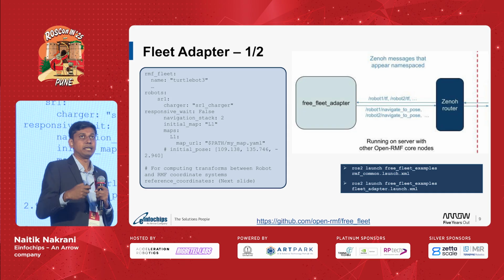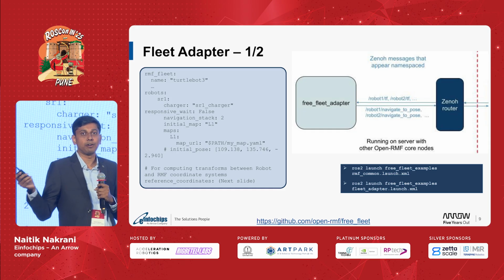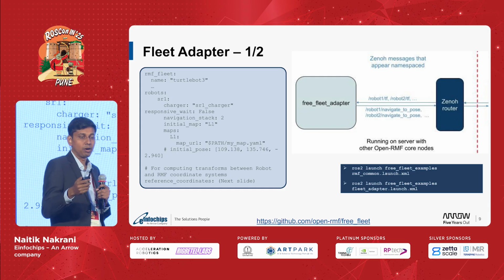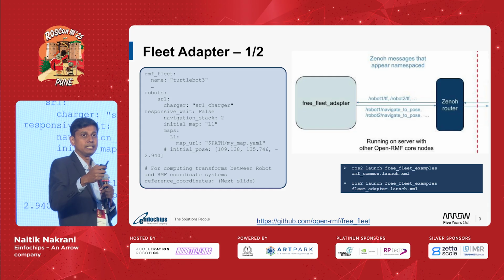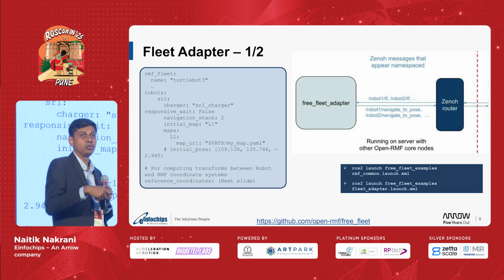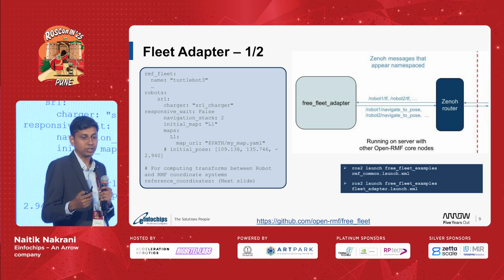Mostly it needs data like what kind of fleet or what kind of robots we are adding, because typically in the earlier implementation of OpenRMF, without the Zenoh introduction, there was a problem of how you can distinguish different kinds of robots. So you might need to use namespaces. Those who have worked with different robots might know about namespaces. And then a lot of challenges happen due to DDS limitations. Because Zenoh was introduced recently, the OpenRMF fleet adapter implementation is pretty easy for multiple robots.